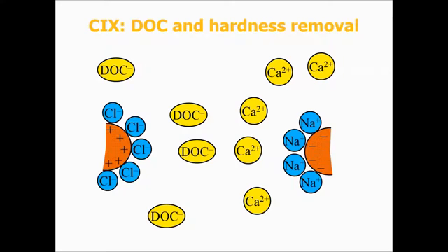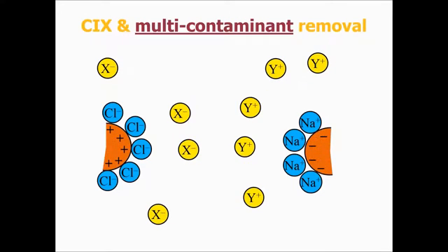So dissolved organic carbon, most are aware, is a concern because it's a disinfection byproduct precursor, and it also exerts a chemical demand through the other stages of water treatment. So there's many compelling reasons to remove DOC and get high levels of DOC removal. Hardness and calcium hardness isn't a health concern, but it is sort of an economic concern and an aesthetic concern during water treatment. And there's many water plants who remove hardness, and so we saw this as an opportunity for, again, this single process to remove multiple contaminants.